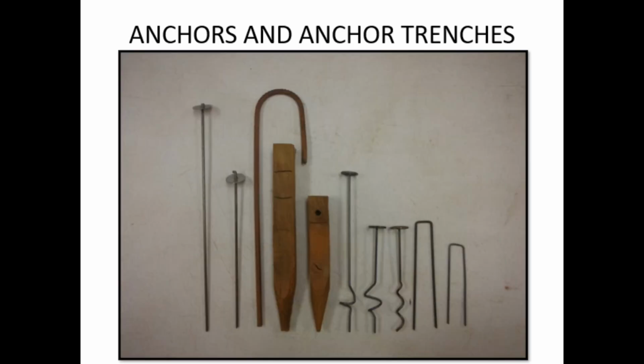It is important to note that performance of an RECP is heavily influenced by anchorage. Flowing water induces attractive shear that tries to peel the product off the soil. Thus, it must be adequately anchored. Early installations used wooden stakes, but the search for economy soon led to the use of light-gauge U-shaped staples. More recently, specially designed anchors have been used more frequently, especially when high flows are expected.